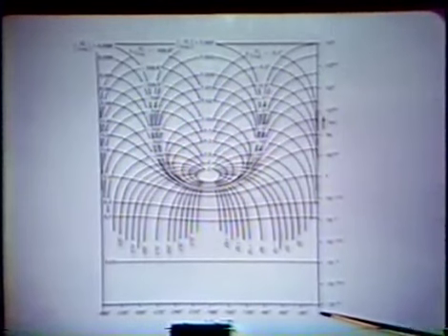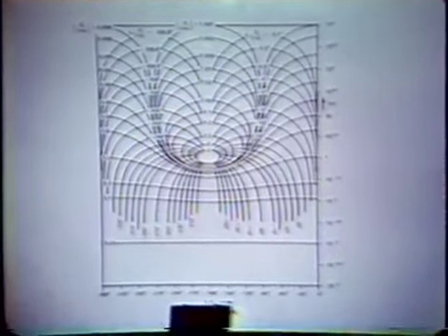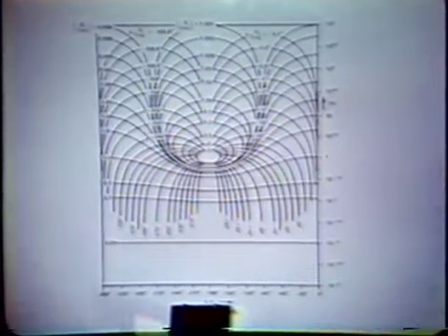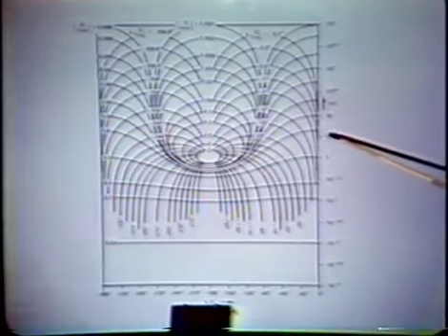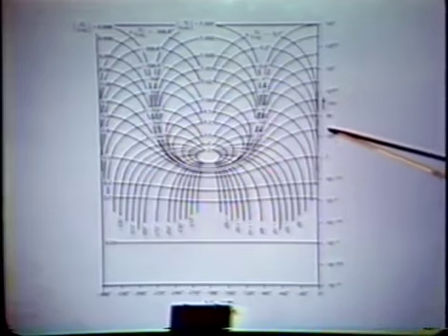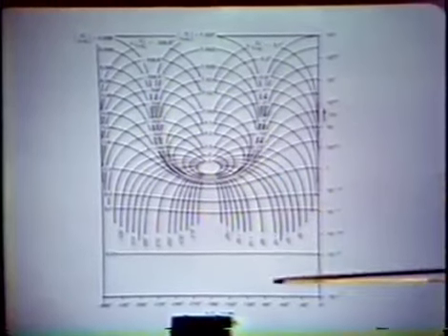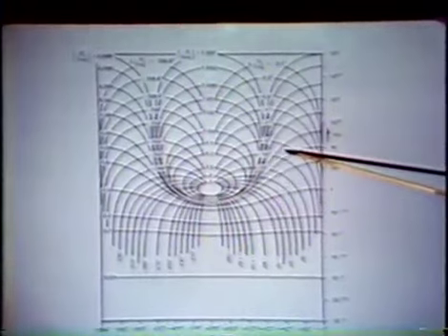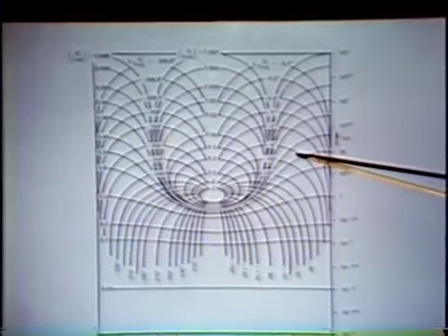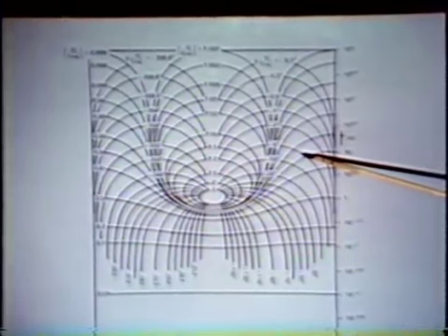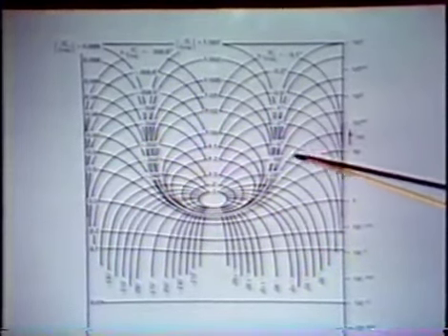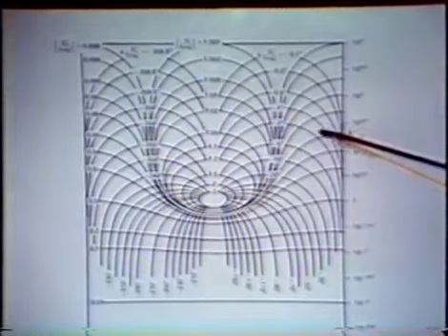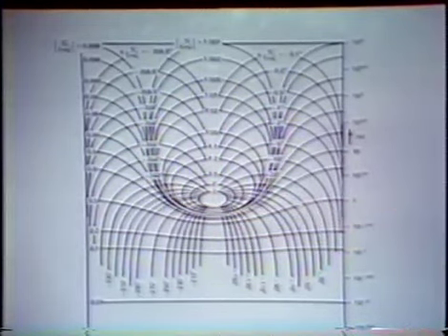Here we have an angle of G running from 0 degrees to minus 360 degrees, and this plane repeats every 360 degrees, so we have all the information that we need. And what we're able to do is go in, for example, if we have a G of 10 and an angle of minus 60 degrees, that's a point in here somewhere, and we can determine corresponding values for G over 1 plus G from the coordinates, the curved lines on the figure.